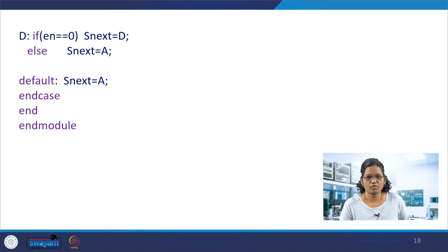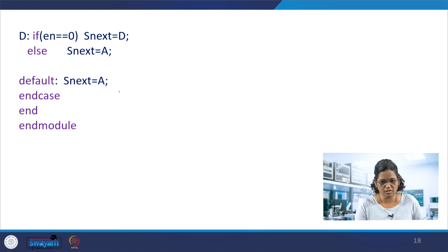If you have one always block, it is easy, and it also minimizes the code, as the sequential execution can be made in the same block. Sometimes having 3 always blocks is better, with the sequential logic in a separate always block and the combinational logic in another, in a particular digital circuit. So this gives more ways of coding the finite state machine in different styles, and the Verilog modules can be made.